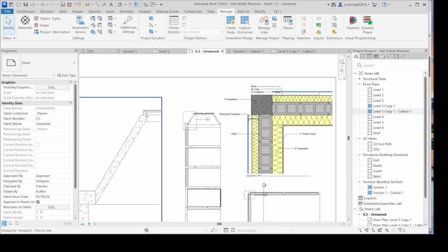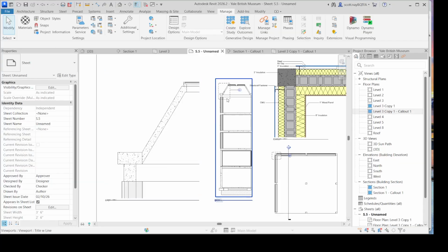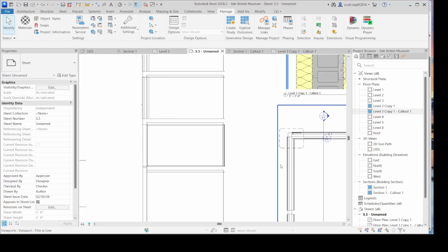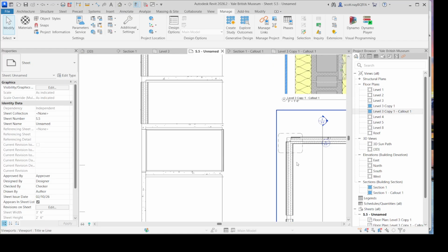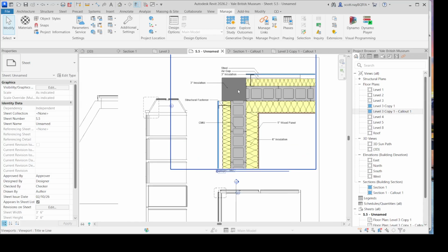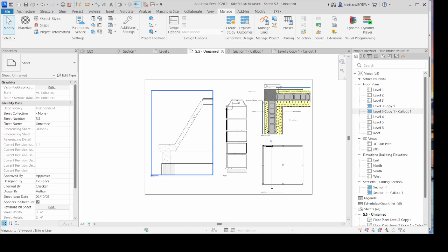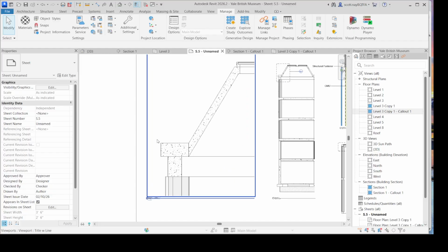So what am I going to do with this? Again, color consistency. Try and apply the same yellow to anything that would be insulation in either here or the section. Same grays for your CMUs. Not this blue, something else for your steels. But we need to add some insulation on here. We need to add a steel covering, and we need to add some sort of flashing to keep water from coming back in.